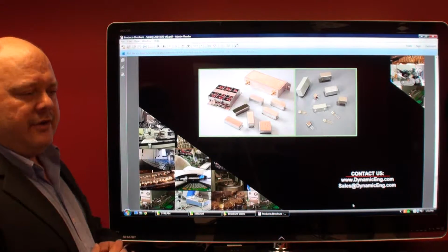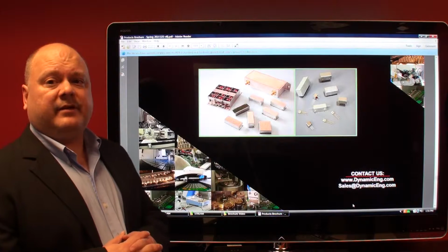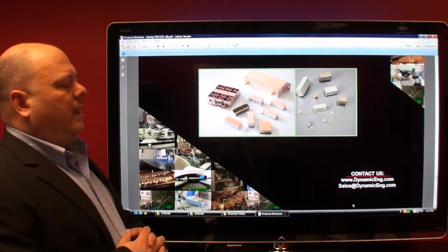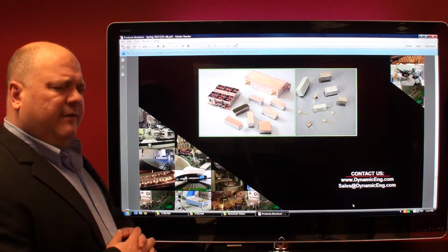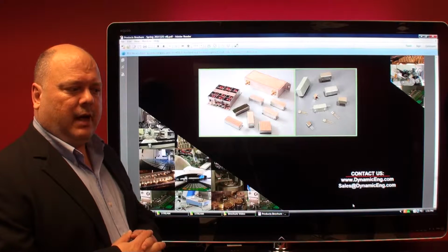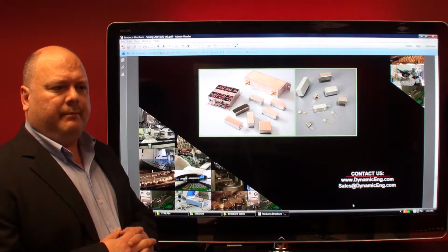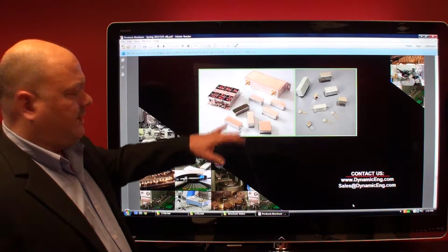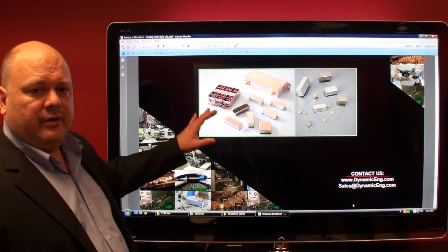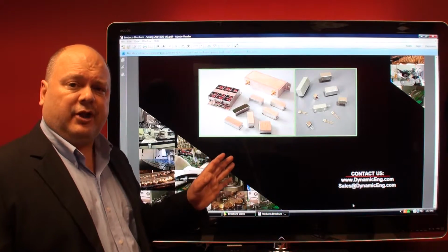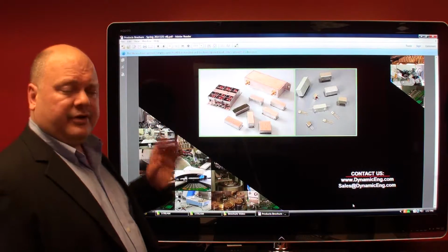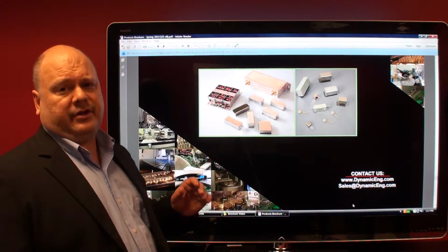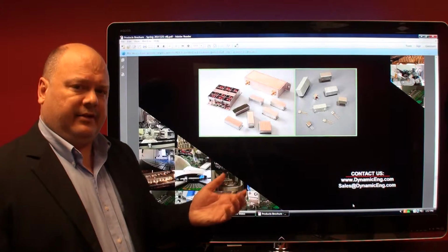In continuing our discussion on the general aspects of crystal and LC filter products from Dynamic Engineers, the other very, very important aspect that is of high value to our customers, back to the 100%, almost 100% vertical integration. So we have the metal cans, as I discussed earlier, the metal packaging configurations, all done in-house with our in-house machine shop. The other aspect of the crystal filters is the fact that the Mesa blanks or the AT Cut crystal blanks, they come in as raw blanks.